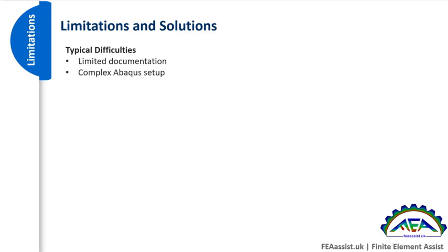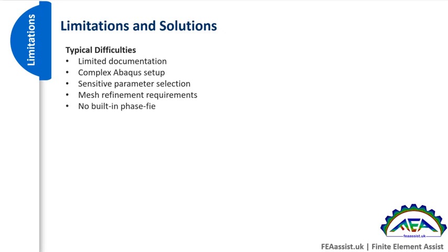You need to know where to use finer mesh and how to apply correct boundary condition. And the results will be sensitive to parameter selection, so you need to know well how to calibrate your parameters and the mesh refinement requirements. Abaqus doesn't have a built-in phase field model, so you need to write the equations and the model in the UMAT subroutine.